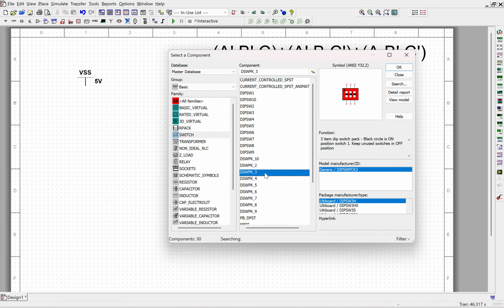We're literally going to repeat this process for the next 3 expressions. Now we can speed this up a little bit by copy and pasting your gates. So if you click on your AND gate, press Ctrl C, you can then just copy and paste it further below. Now I've done that for the next couple of AND gates, and then what we can do is just basically link them up the next way.